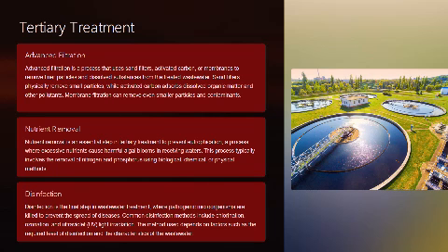So you want to remove nutrients in these instances, and that is what the tertiary treatment equally is about. In order to do this, you typically involve the removal of nitrogen and phosphorus by using biological, chemical, or physical methods.